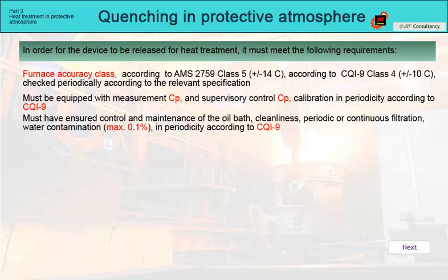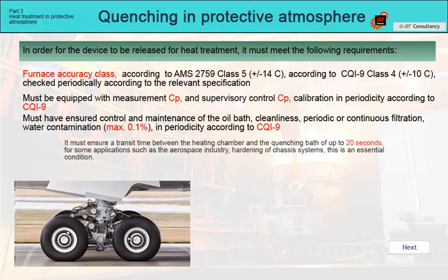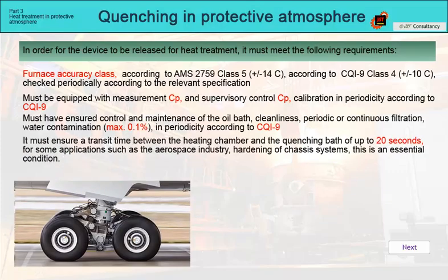It must be ensured that the time of the batch transfer between the heating chamber and the quenching oil bath, from opening the door to capturing the entire batch in the oil, is within a defined time. And for some applications, such as the aerospace industry, it is essential to achieve this in 20 seconds.